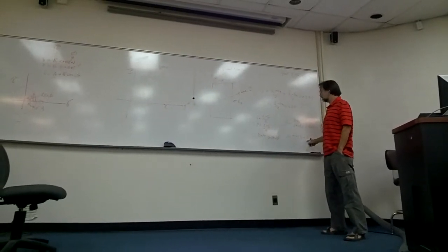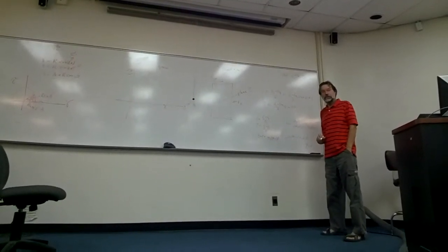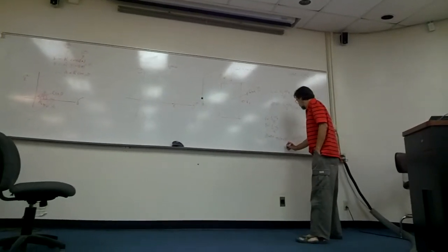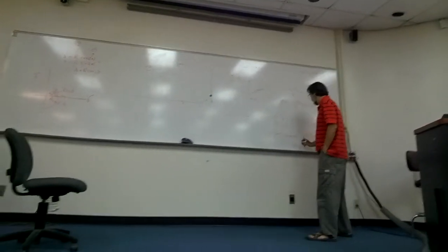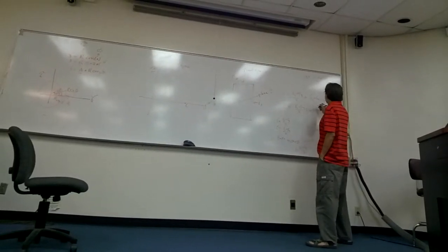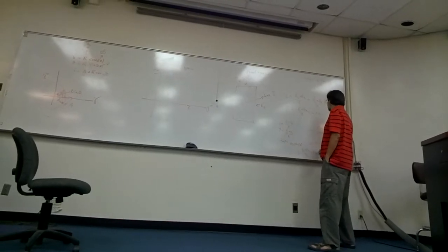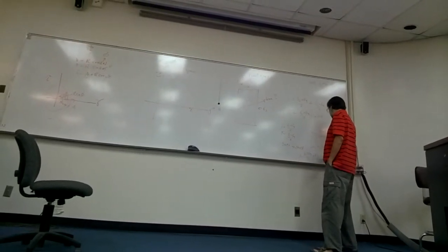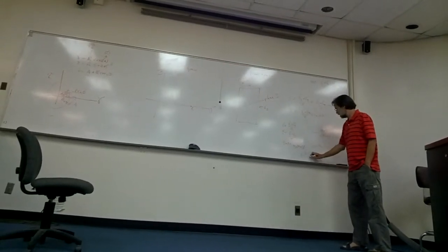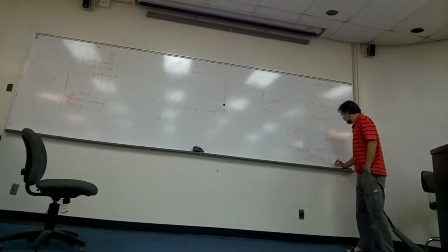So tau is going to be 0, right? If cosine is negative 1, I now have sigma equals sigma 1 plus sigma 3 over 2, but this is now negative 1, so it's plus sigma 3 minus sigma 1 over 2. Now the sigma 1's cancel, and I've got sigma 3 over 2 times 2. This becomes sigma 3.